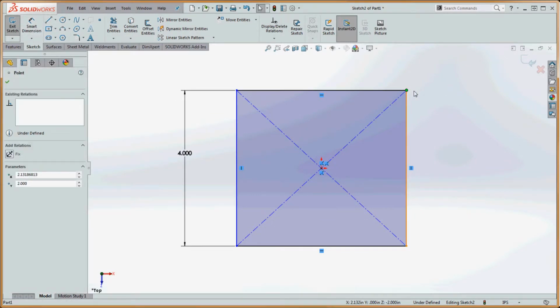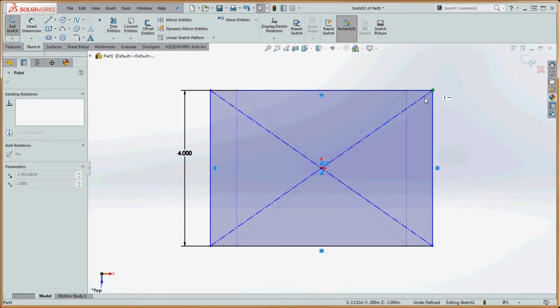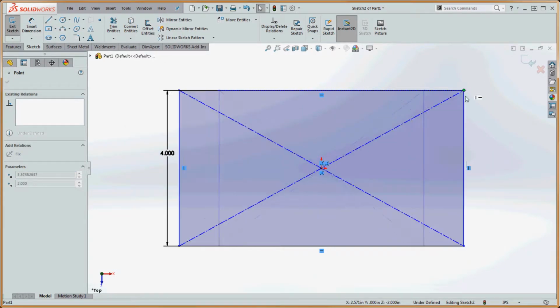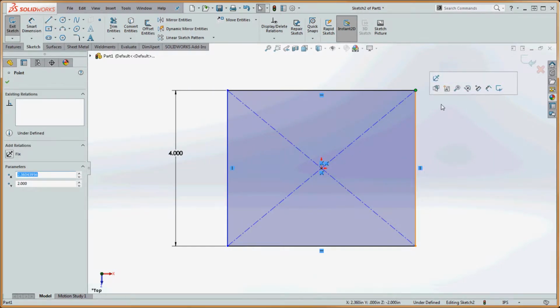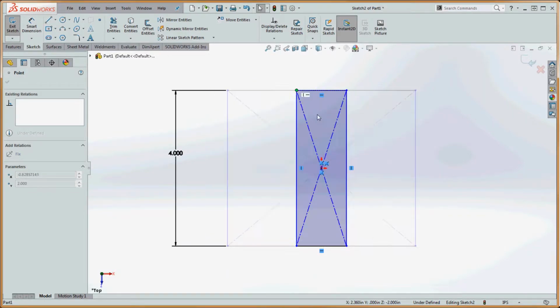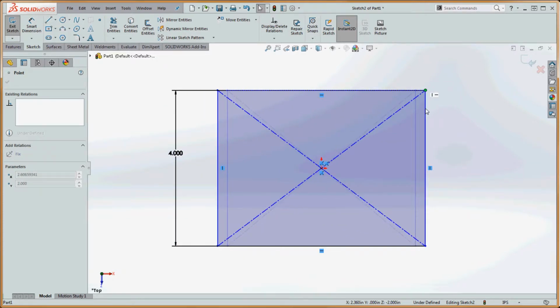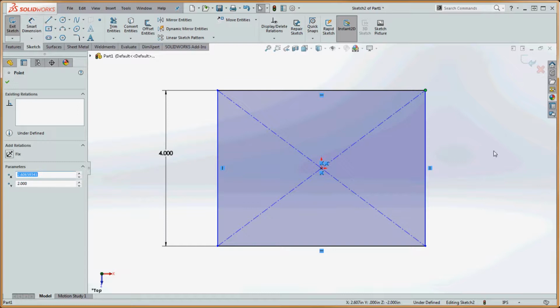And if we grab that point and move that, you can see that the line is always going to be 2 inches from the front plane, but the endpoints in the line have not been defined, and they could be defined. And this is what I mean about the model potentially moving on you later and causing an error, because you can take this point and actually move it over here. It kind of looks like it's spinning around a little bit, but there are parts of this sketch that you're looking at that have not been fully defined, and we're going to go ahead and do that.